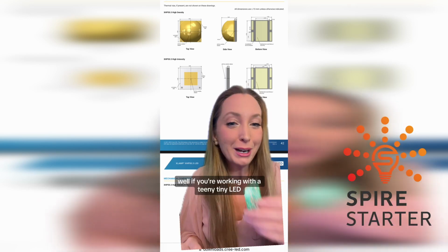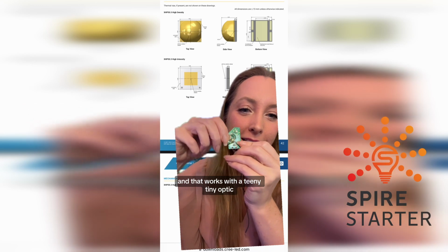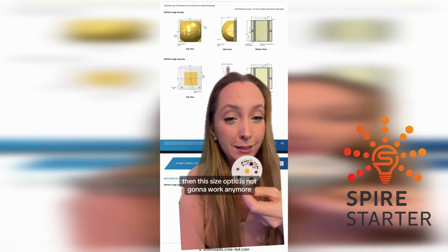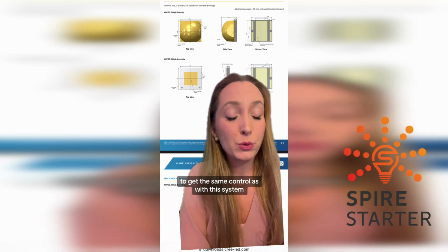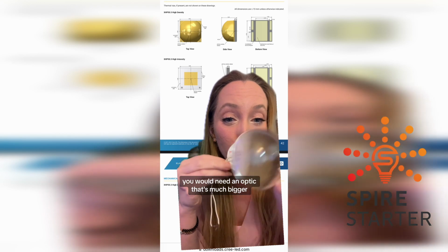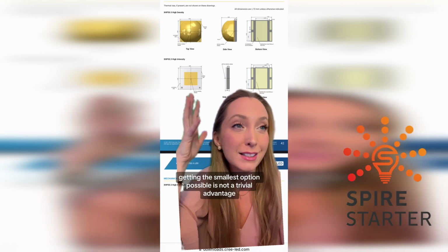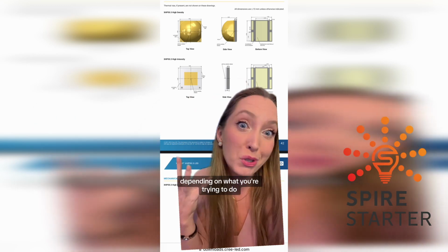What do I mean? Well, if you're working with a teeny tiny LED and that works with a teeny tiny optic, if you move instead to an LED like this size, then this size optic is not going to work anymore. To get the same control as with this system, you would need an optic that's much bigger. And usually that's not something product managers like to see. So getting the smallest option possible is not a trivial advantage, even sometimes to tenths of a millimeter, depending on what you're trying to do.